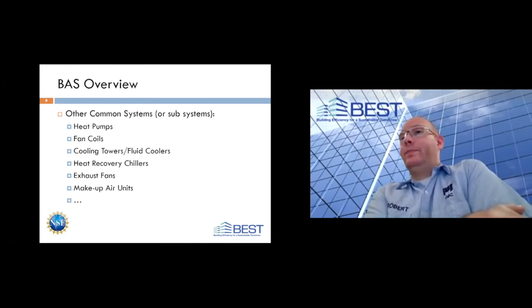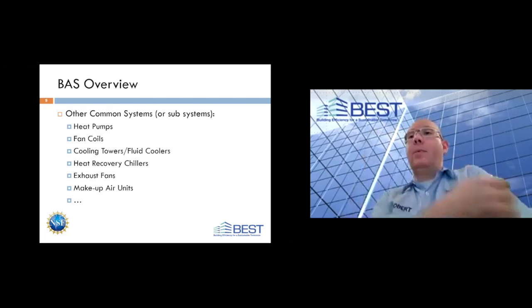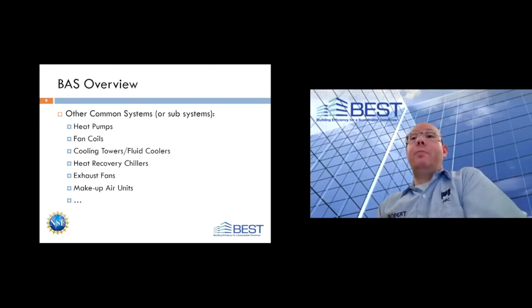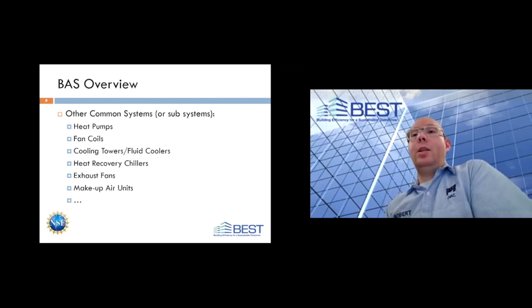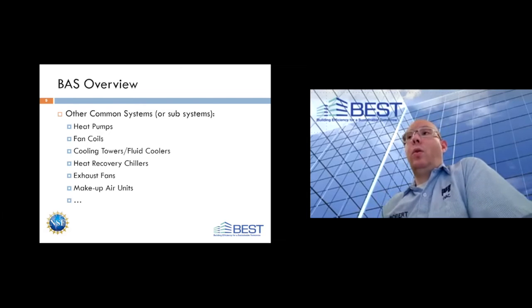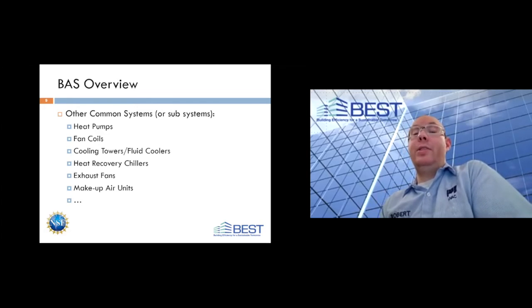Exhaust fans definitely show up in almost every building, if for nothing else than bathroom exhaust. They don't typically get their own control, though depending on what they're doing, they may. They may be based on schedule, they may have a rotary time clock on a wall, or they could be an extremely advanced negative pressure HEPA system for isolation rooms in a hospital, or chemical hoods. The applications for exhaust fans is a presentation all in itself.